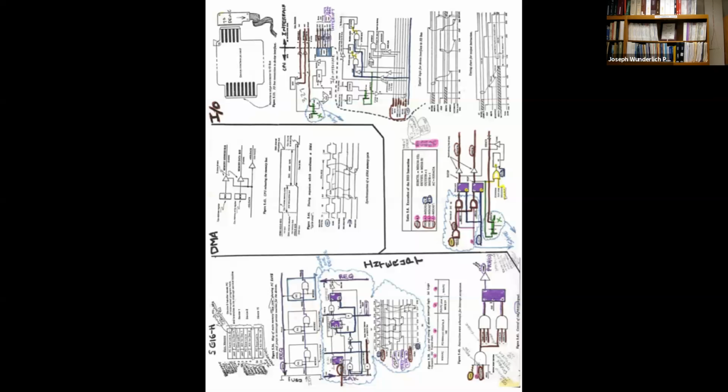When you connect to a bus, you can't just connect a wire directly to the bus, especially if you have a million things connected to the bus. They're all sharing the bus. I mean, a bus sounds like a thing full of people, right? The bus is actually the roadway itself and the way you connect to it, and you have to disconnect all the branches. You can't have them all feeding at the same time. We're talking about electricity here, so you can burn things out if you have everything activated on the bus at the same time. So you need tri-state buffers, and that's some of the reality.